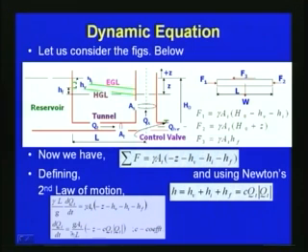Finally, we can write this relationship as dQt by dt is equal to G into AT by L into minus Z minus C Qt into modulus Qt, the modulus taking care of the direction of flow, where C is a coefficient. Here Qt is the discharge through the tunnel, AT is the cross section area of the tunnel, L is the length we consider from here to here, C is the coefficient, and Z is the datum, the head difference here with respect to this.